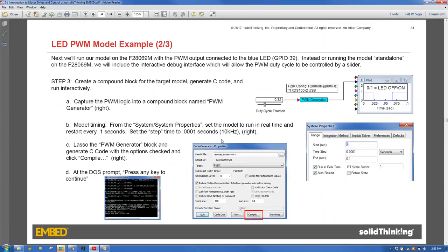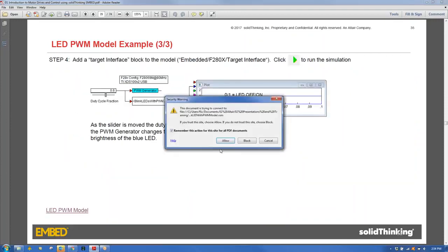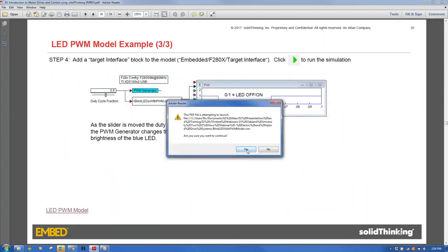Because this is going to be occurring so rapidly, the LED is going to have some inherent capacitance to it that's going to smooth this out, and it's going to respond to the average value of that PWM signal. I'm just going to basically allow it to dim and brighten. So let me bring up the model that does that.